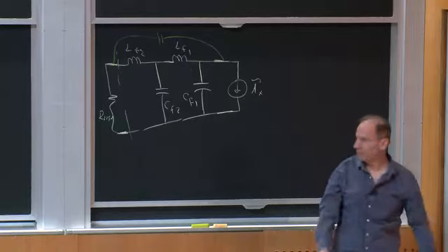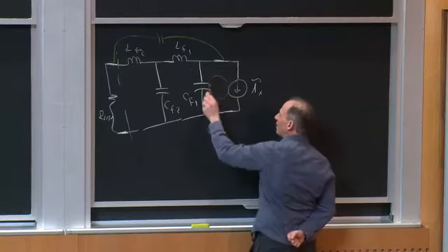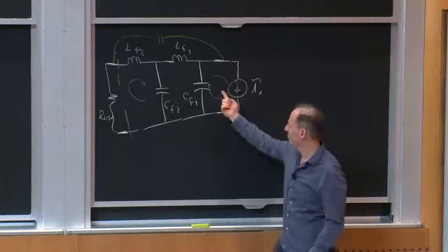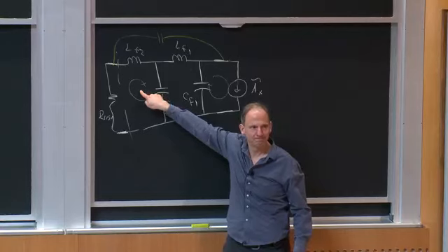You can also have magnetic bridging. If this loop with a lot of switching ripple has mutual inductance to this loop, even if there's no capacitance, I can get magnetically coupled right across through my layout, okay, and completely ruin my filter performance.